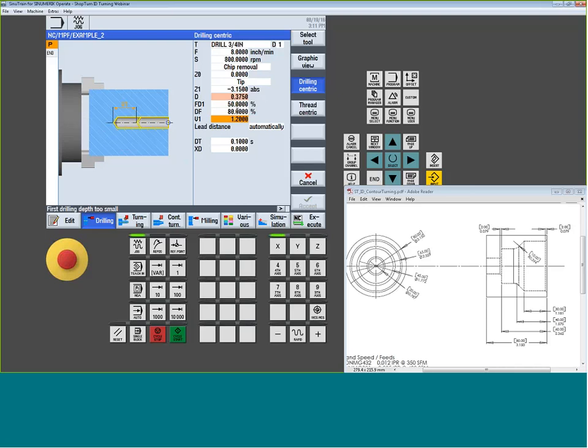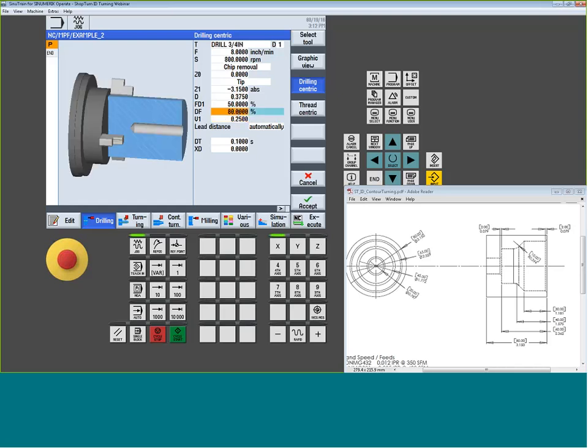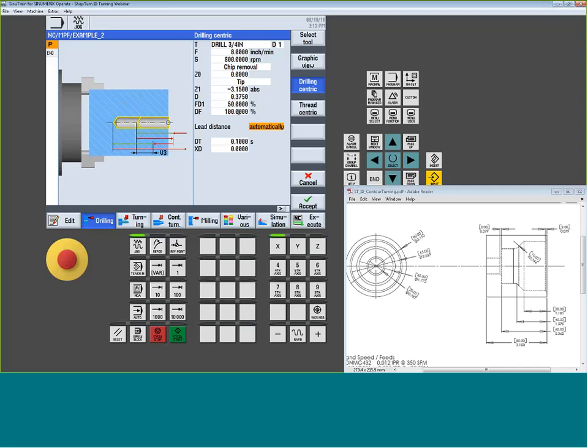Now, once it sees that my peck value is decreasing, it does give me a minimum peck amount. Now, in this case, the system is saying, hey, your minimum peck is greater than your actual first peck, so it doesn't like that. So I would have to change this to something smaller, so in this case, it'll start dropping the peck until it reaches 250, and then maintain a 250 peck until the end. If you don't want to decrement down, if it's not super deep hole drilling, usually you don't have to, then I would leave this at 100.